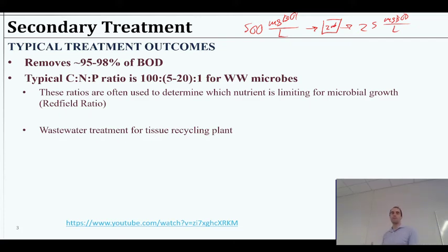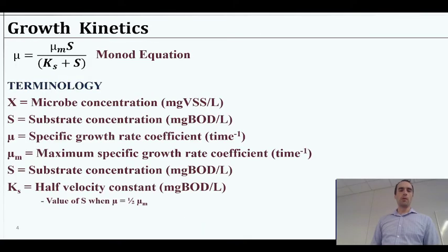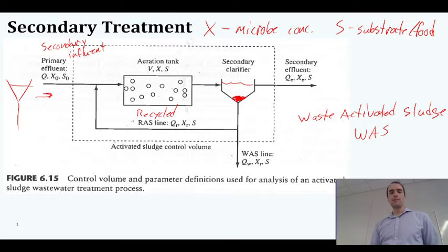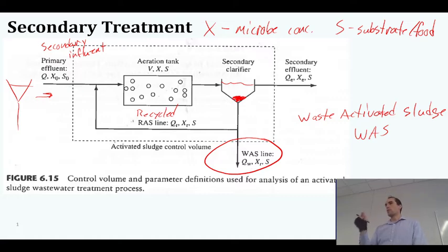Lots of bad things will happen because of that, because in part then we're not recycling appropriately. We're no longer managing the concentration of bacteria the way we designed it for. So we'll see that as we move forward. I'm going to take a quick step back. When we consider this graph, it turns out that this waste activated sludge line that takes that bacteria that has been clarified, controlling that one parameter turns out to be very important to the effectiveness of the whole system, because it's controlling how long the bacteria stay in the system.